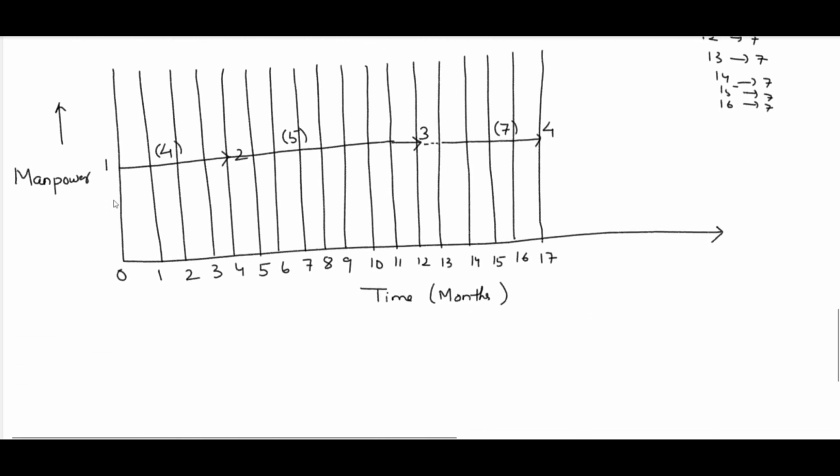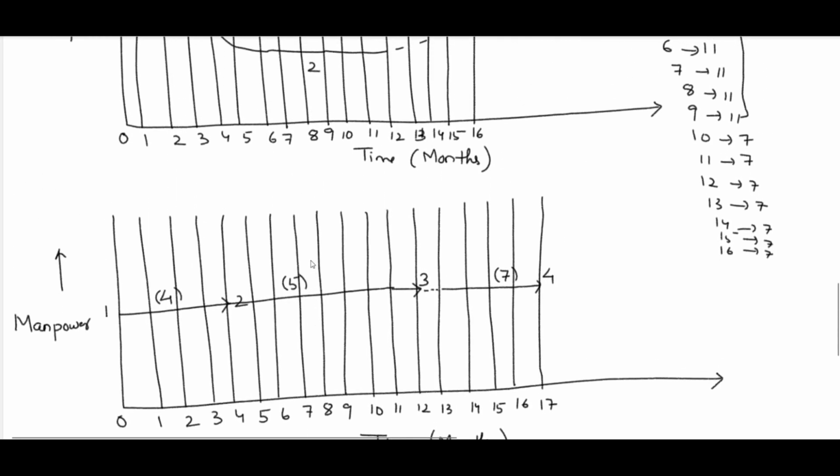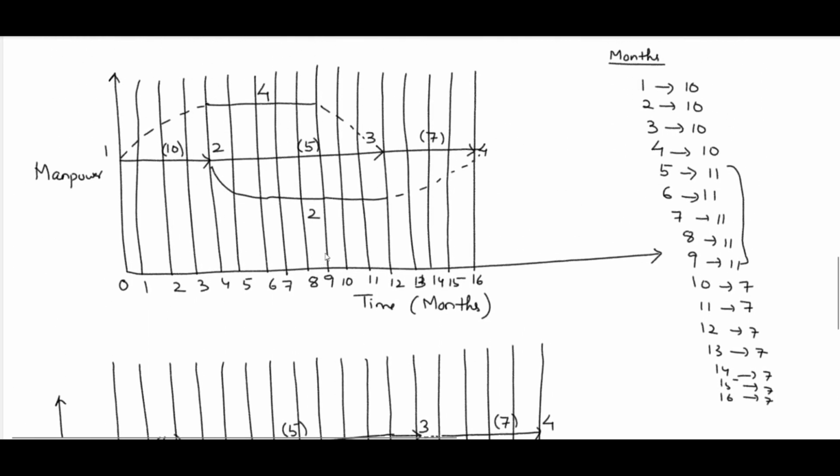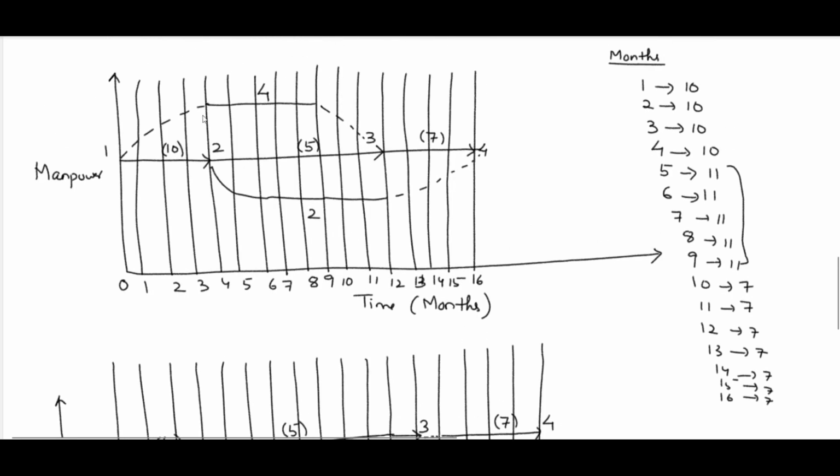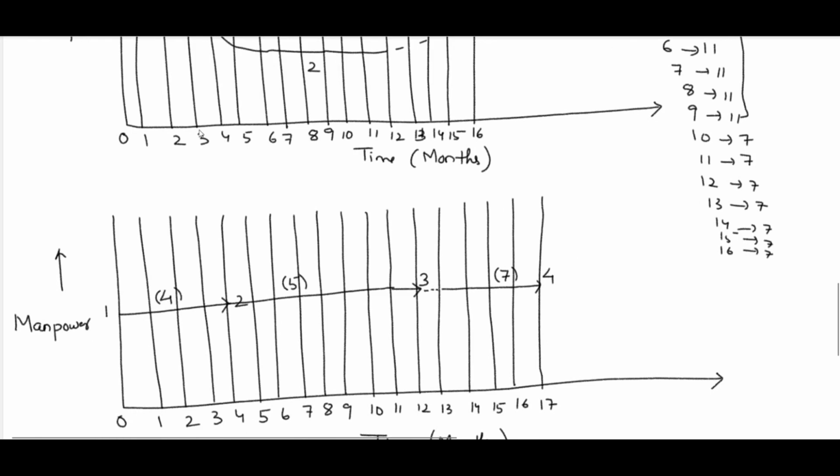So that's why I have taken it like this, with a dummy, and activity 1 3 remains the same because we have shifted correctly. Activity 1 3 will start from here. Activity 1 2 takes 10 as manpower, and 4 is the duration.